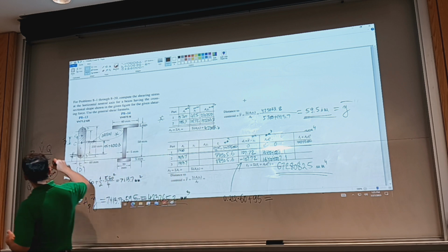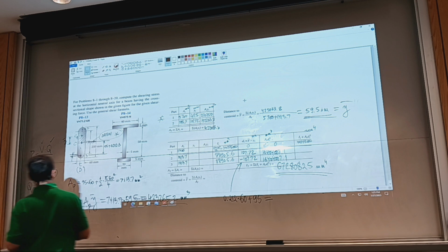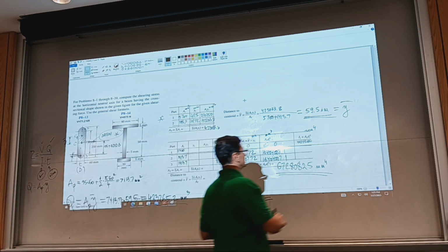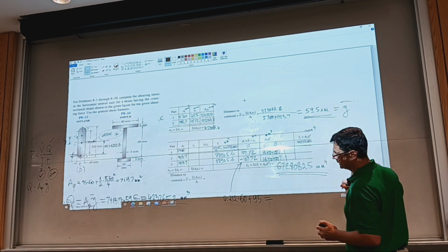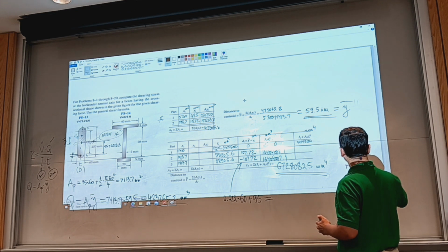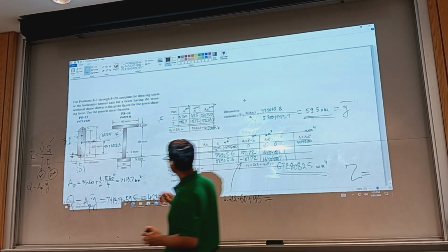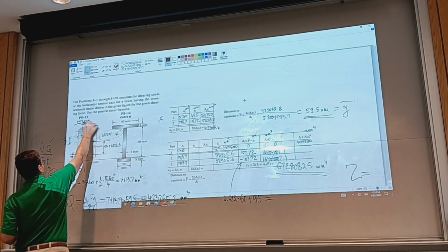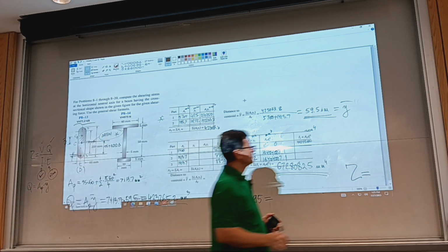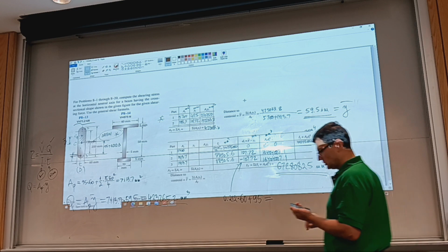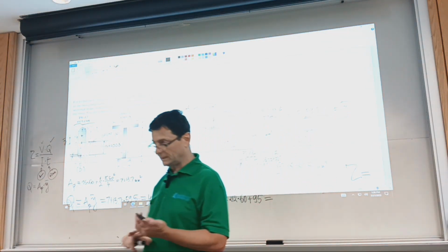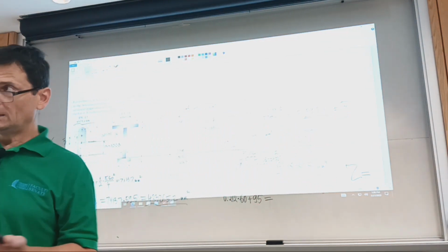So really we have everything, after so much labor, to evaluate shear stress caused by the shear force. Again, this is given in the text of the problem. Remember, to get shear in megapascals, you need to work with millimeters and newtons.